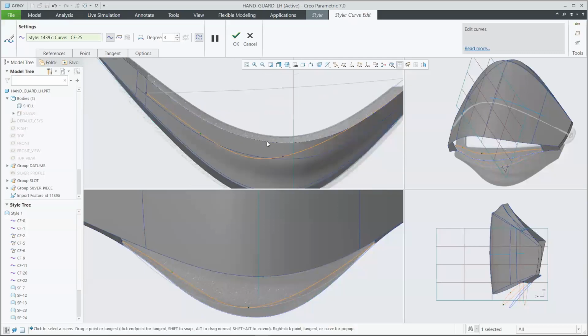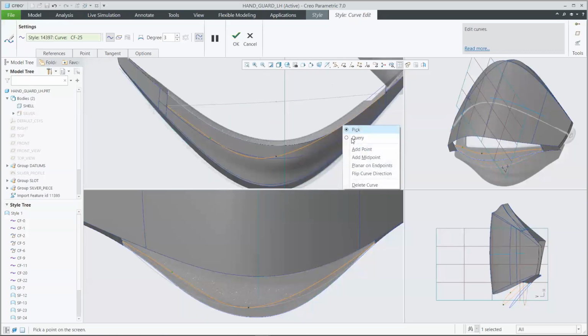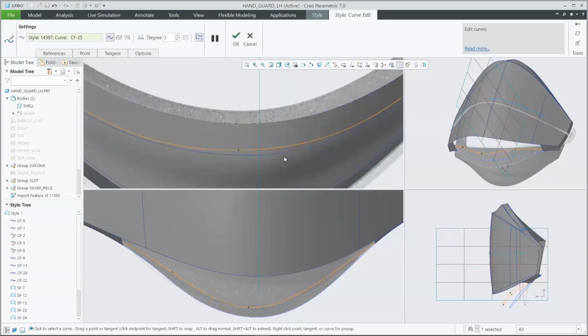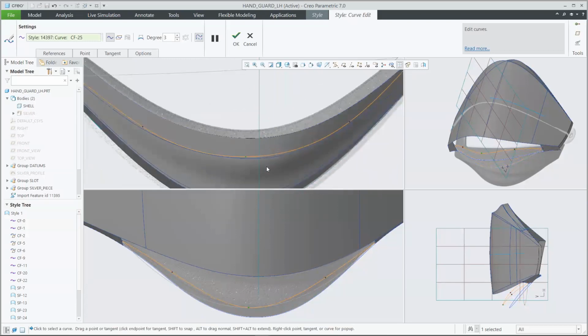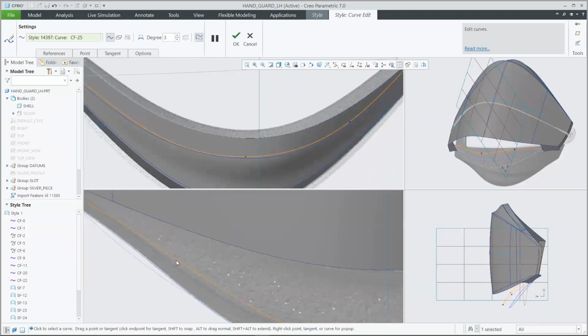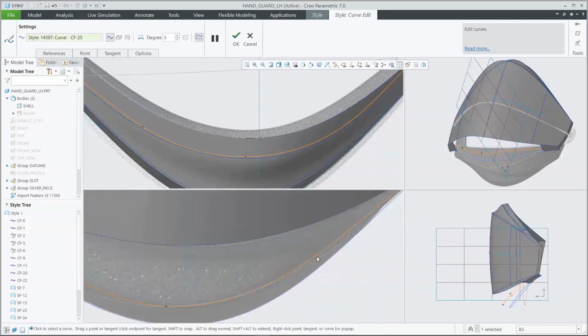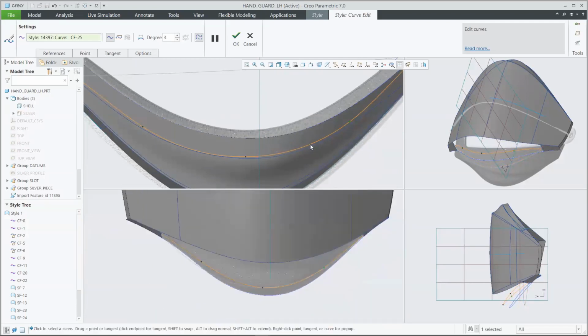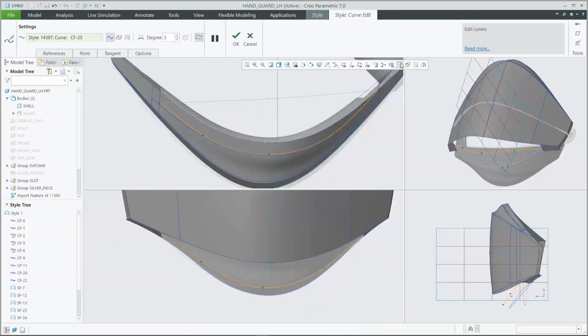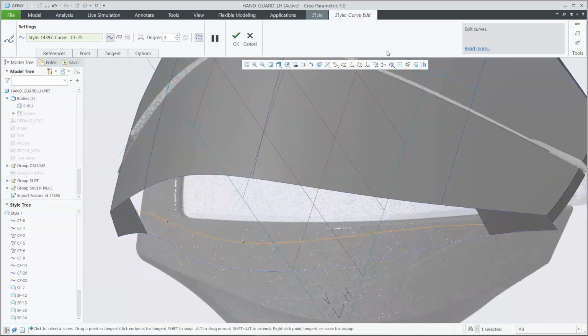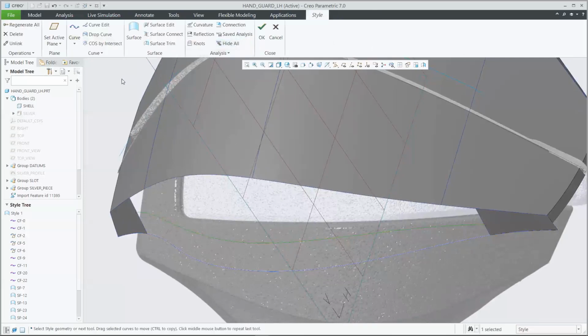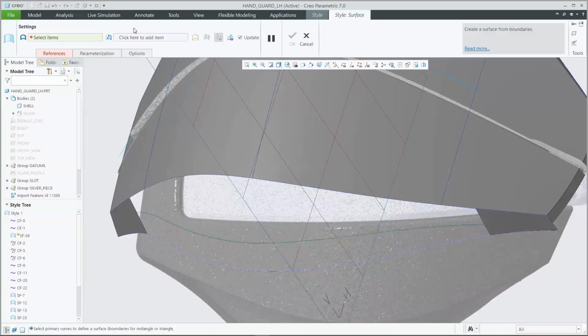So here, just making sure, again, that our center curve is aligning well with that initial sketch that we started with. And that's looking good. We can go ahead and fill in that first area down here at the bottom with the new surface once we have this all laid out. And again, you don't necessarily have to always match up exactly with what you have in the sketches. You can just use that as reference and work off of that if you'd like. And this will work similar to how we did with the other 2 surfaces, by selecting the 4 curves along the outside.